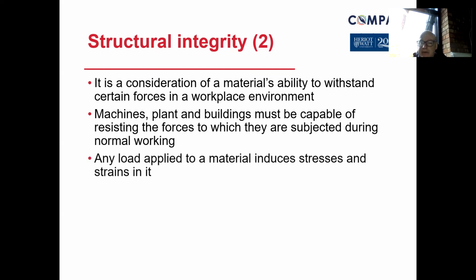Any load applied to a material induces stresses and strains, and we would question how much of that it can return back to its original state. So if you think about thorough examination, for example, in lifting operations, lifting equipment regulations, if we use a chain as an example that's been used in a load lift, if the link, should we say, is a typical shape, kind of like that shape, maybe it's stretched, and by visual inspection you can see that it's not the shape that it should be, and therefore is it capable now of doing the job it did before?